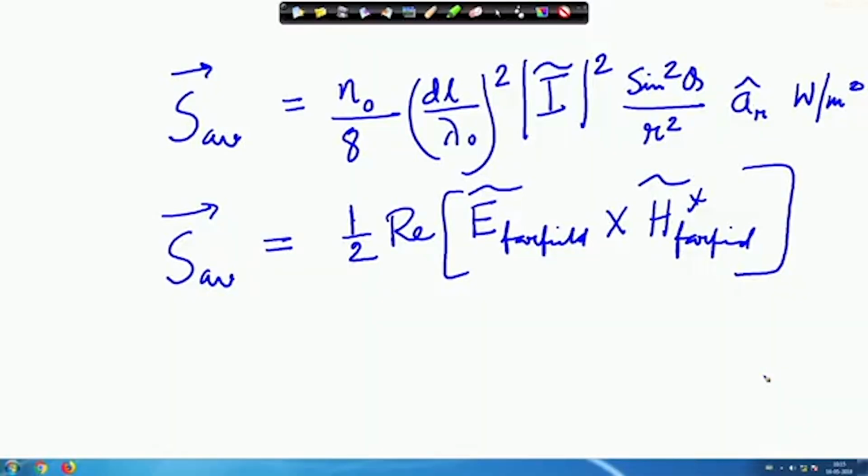Usually it is a plus J component of power, that is why they are called inductive fields, as if in an inductor there is a local storage of energy. That energy does not flow in a typical circuit also. So, here also near the antenna there is an energy storage, but that energy is not flowing. Only after a certain distance that energy starts flowing.